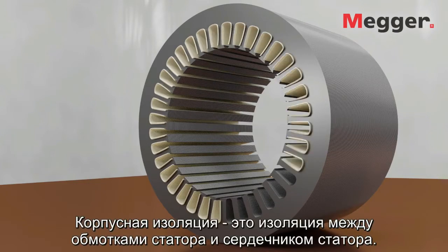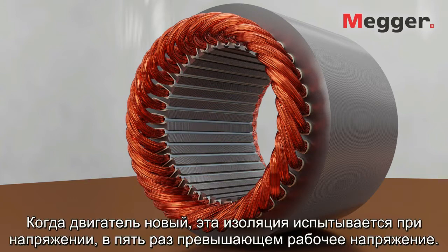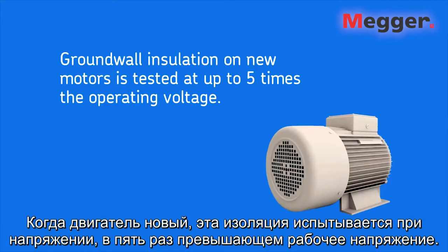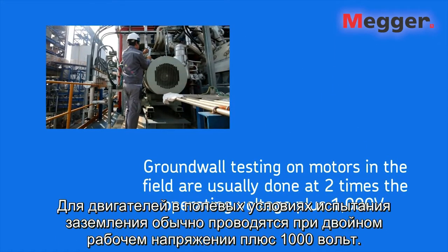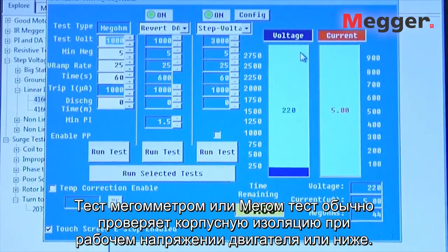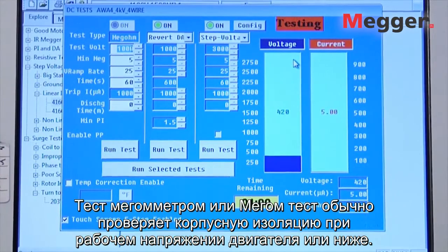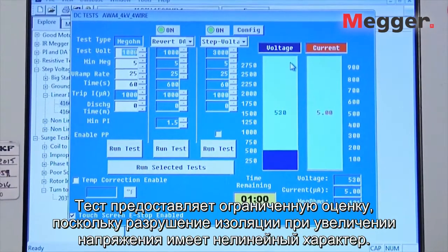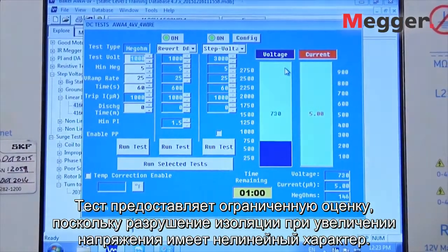The ground wall insulation is the insulation between the stator windings and the stator core. When the motor is new, this ground wall insulation is tested at voltages up to 5 times the operating voltage. For motors in the field, ground wall testing is usually done at 2 times operating voltage plus 1000 volts. A Megger test or Meg-ohm test typically tests the ground wall insulation at or below the motor operating voltage. This has limited value as insulation breaks down non-linearly as the voltage increases.